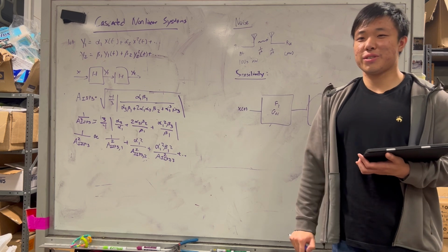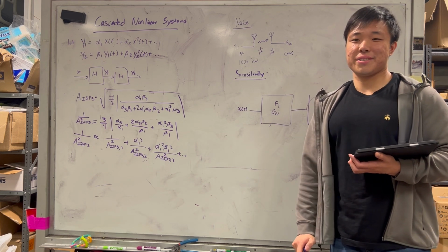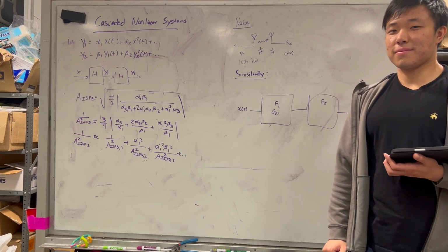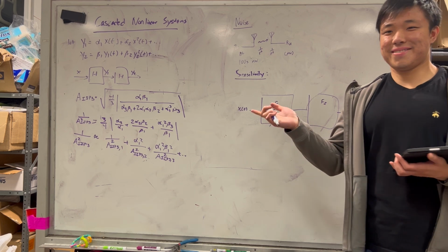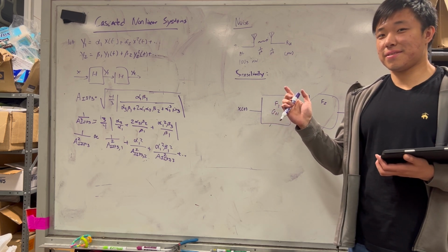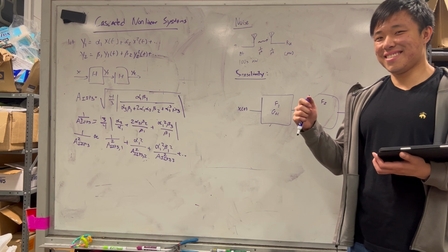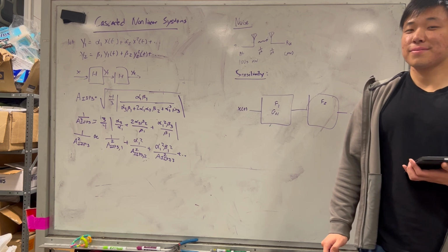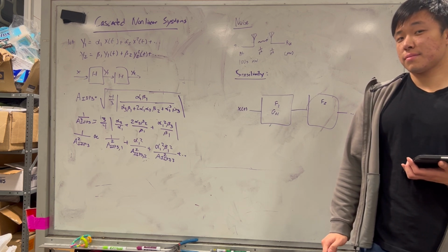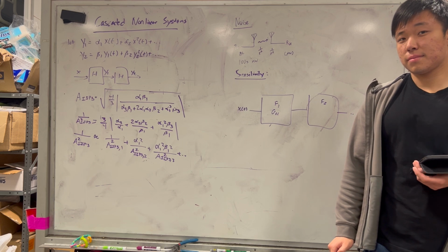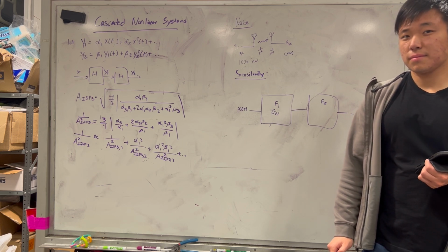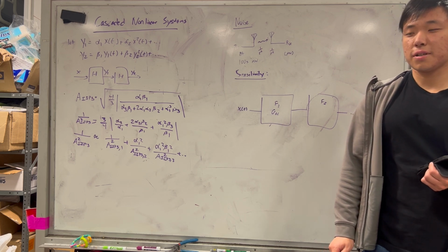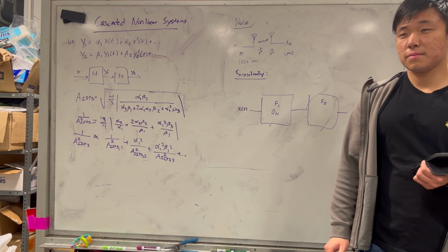Is power gain the same as voltage gain? How is it different? Anyone? You got it? Okay, fair enough. Okay. The matching matters. So it's not just how large of a gain you can see in voltage from side to side, but also how much of the power can actually be transmitted to the load, block to block or system to system or antenna to antenna. So you need correct matching.